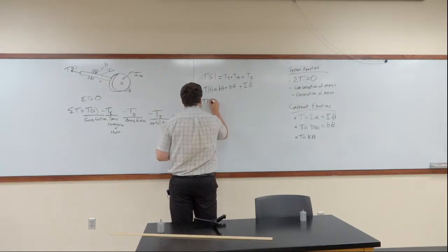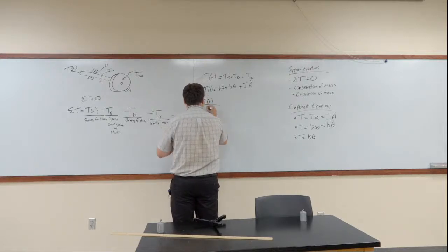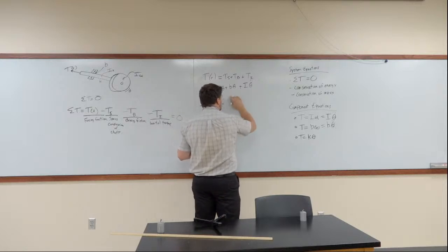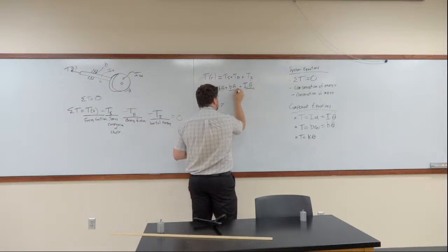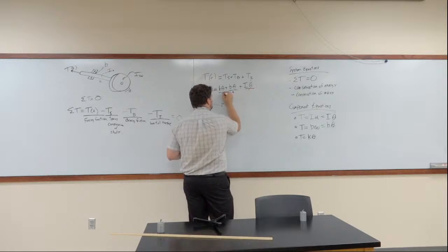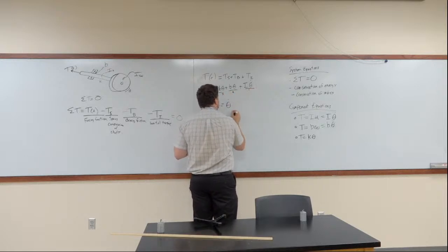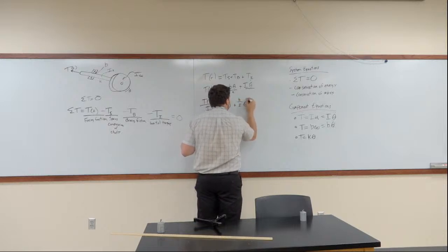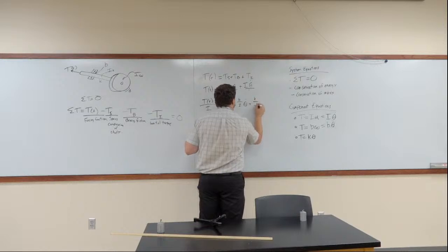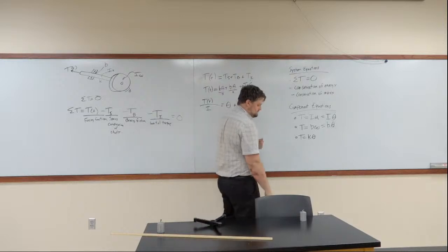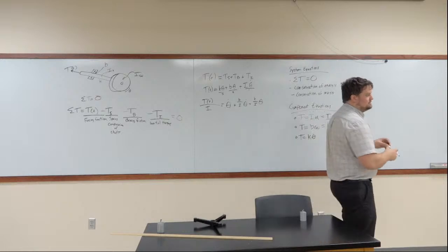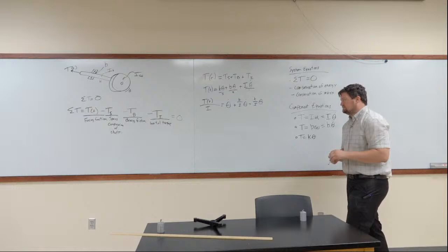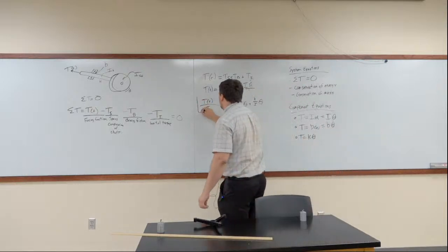So here we're going to end up with your forcing function divided by I is equal to, and then I'm going to rearrange this so that this one's first, this one's second, this one's third. This will be theta double dot plus b over I theta dot plus k over I times theta. This is our constitutive equation. So I'm drawing a box around it.